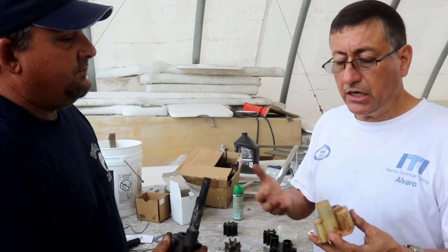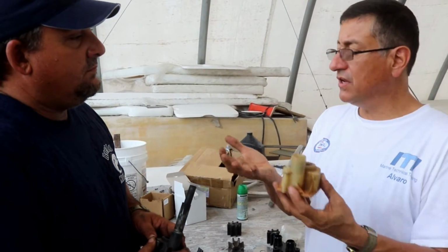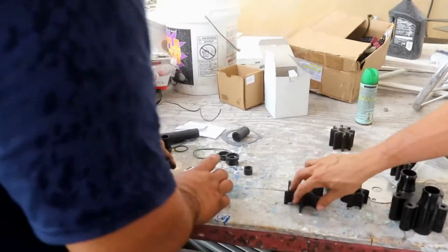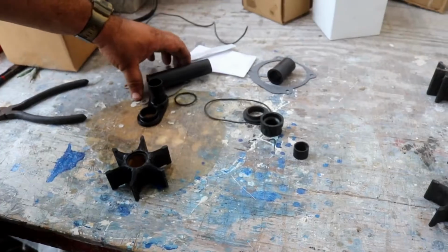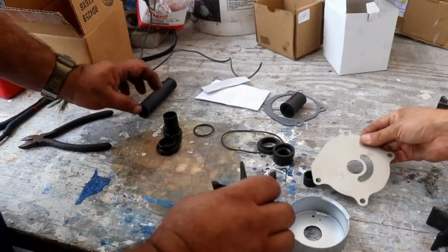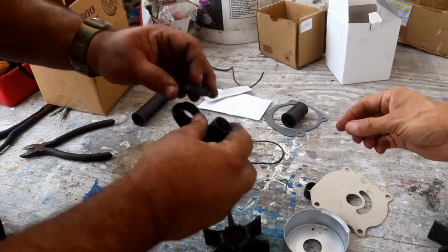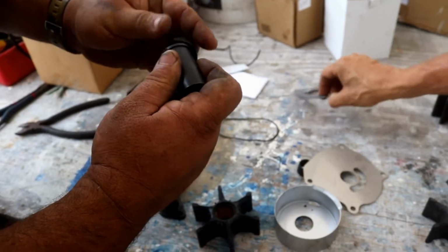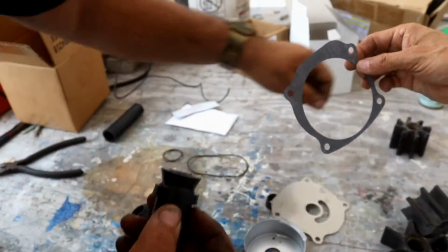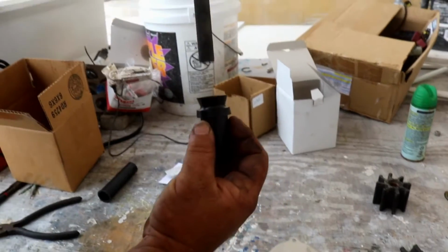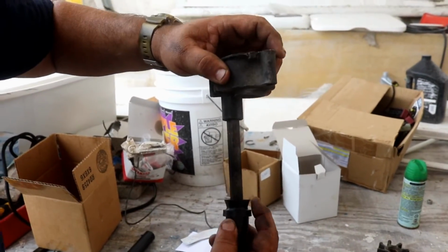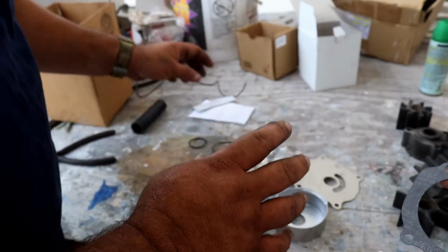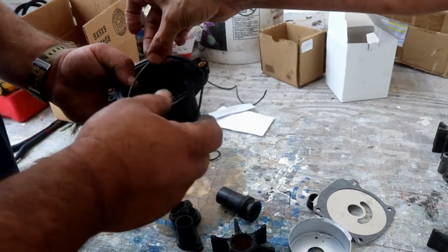Danny, when you order the kit, depending on the model, what do you receive? Here's one kit we have complete. It comes with the housing, the wear plate, the impeller, then the seal you were talking about on top. You have the seal that goes on the water tube. So if your water tube is coming from the engine, it would go in there. And you have to put grease, always. Marine grease. And here's the deal. On the housing, the gasket goes here.